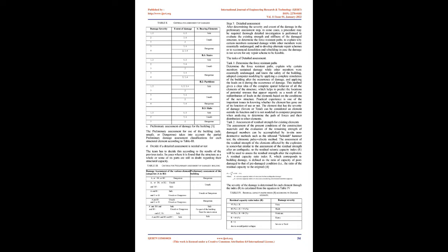D. Decide if a detailed assessment is needed or not. The team has to decide this according to the results of the previous tasks, in cases where it is found that the structure as a whole or some of its parts are still in doubt regarding their structural capacity. Table 3. Criteria for preliminary assessment of damaged building. Damage assessment of the various elements. Preliminary assessment of the building. Step 3, Detailed assessment.